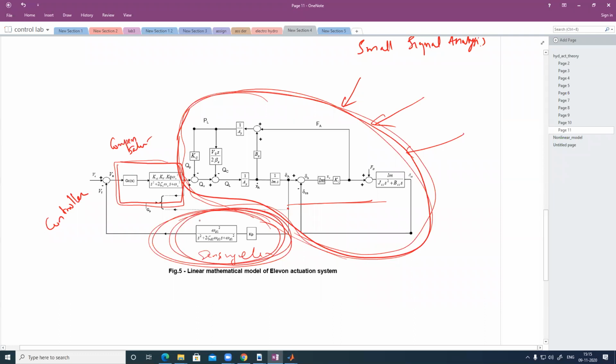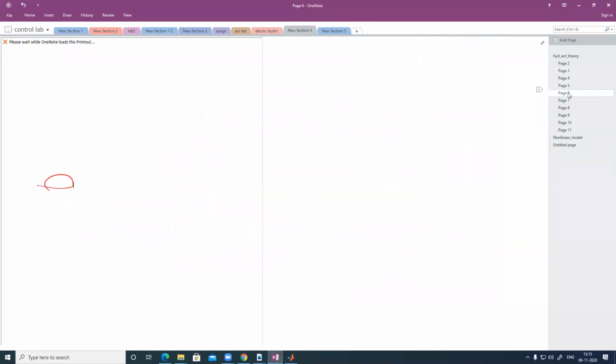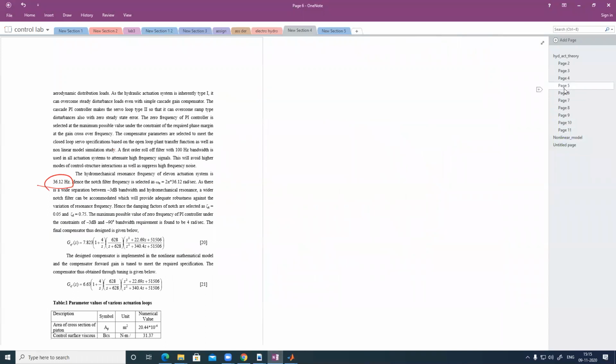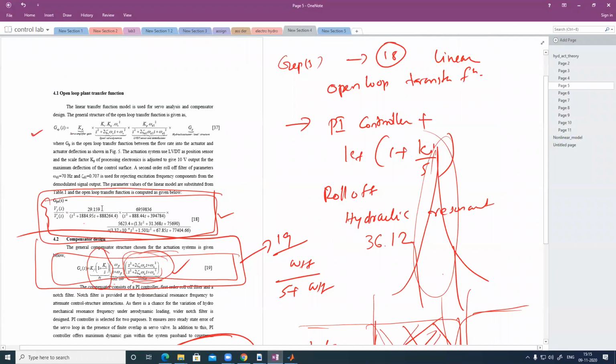So the sensor you have to take here. This omega D1 is closing the loop. So you have to use the closed loop transfer function for that. You enter GP first and this omega D1, and these values you put in, then you have to close the loop. So this transfer function G, that is G upon 1 plus G, is the closed loop transfer function.